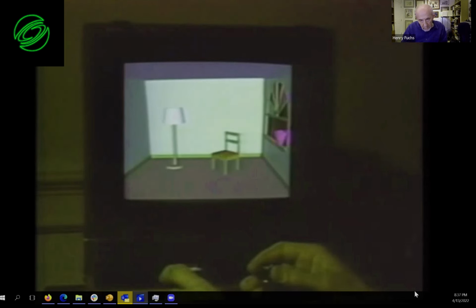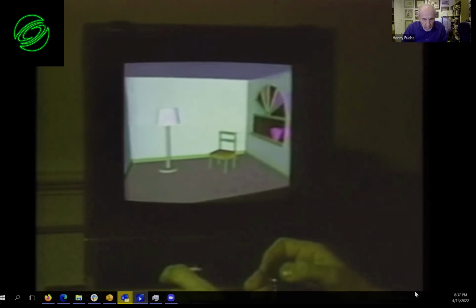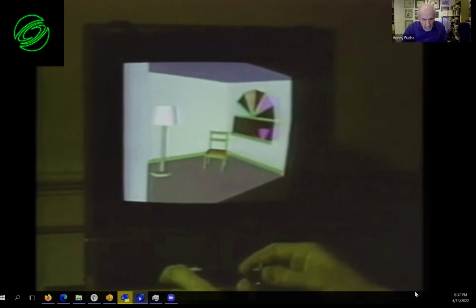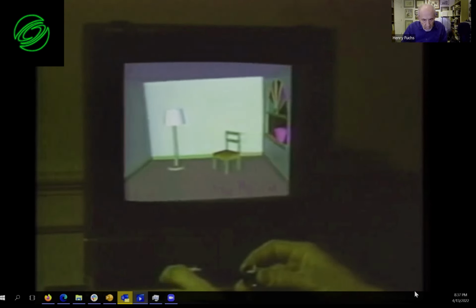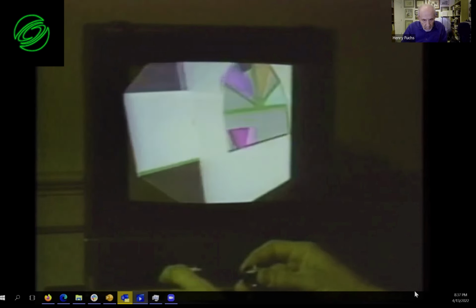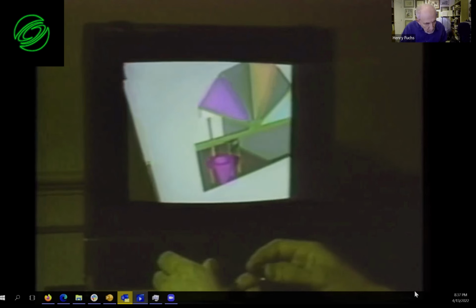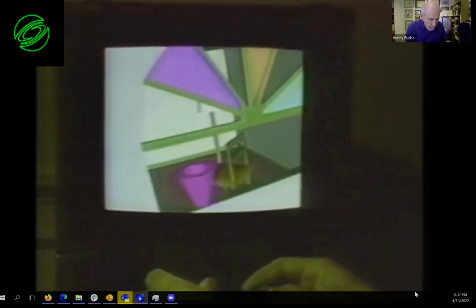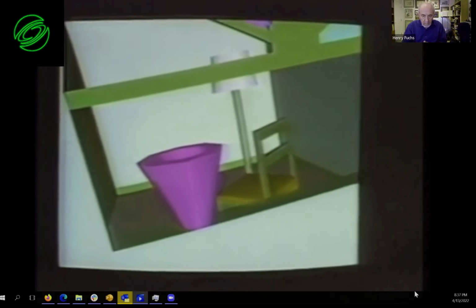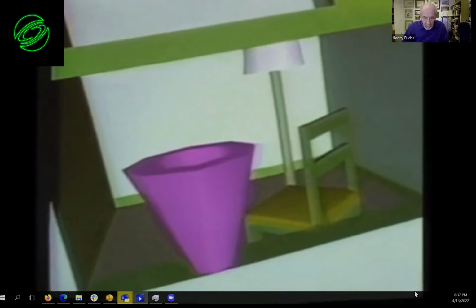Hidden surface calculations using the classic Z-buffer algorithm are also done simultaneously for all pixels in a polygon, using a single A, B, C linear coefficient set. These are the coefficients of the plane on which this polygon lies. Each pixel compares its new value that it receives from the multiplier tree with the old Z value that it's storing in the Z buffer.